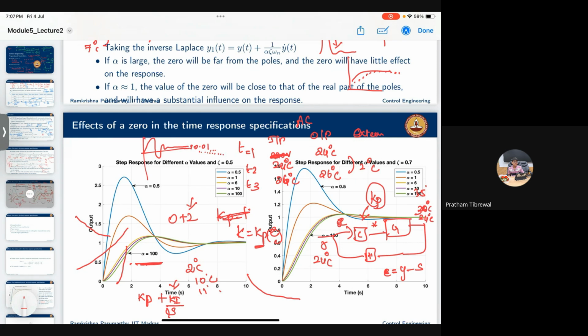After a particular time, it will reach 1. After some time, it will reach 10, 100. So this will create an imbalance in the system. To accommodate this change in the error, it is going to create a very big control action. So that will increase the overshoot of the system. Overshoot means the output response will shoot, like go to the peak.